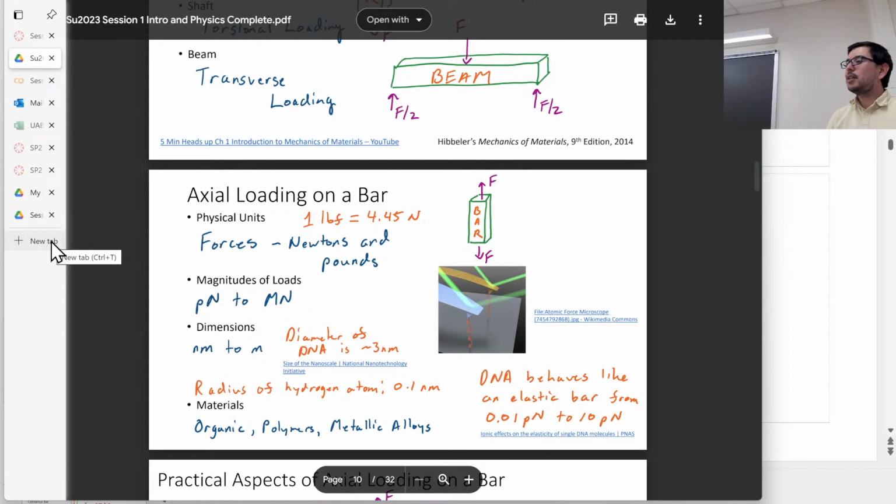Because you can heat treat it, you can plastically deform it, and these things change its strength. And it maintains the same elastic modulus. We'll have a whole thing on material properties, okay? But it's a cool material. It's a really great material. And of course, you can change its composition, by changing the amount of carbon that's in it.